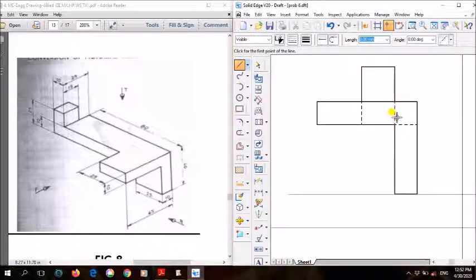That's why we have drawn these two lines using dotted line. And after that, whatever this solid is there, just forget this part and concentrate only on this for this solid. In this solid, two edges are there on that side. This edge is at the bottom side, so that edge is not visible from the right side, right? Hence I drew it using dotted line. Clear? So this is the right view.